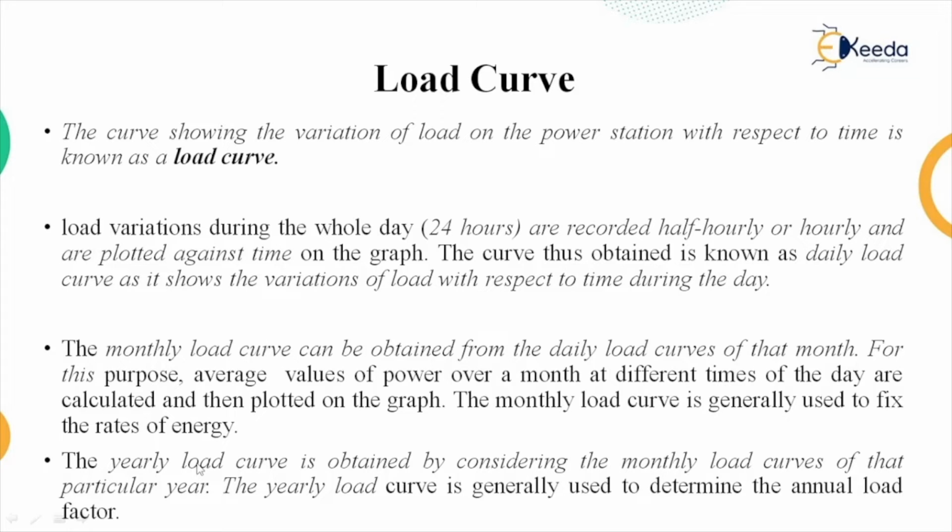Then the yearly load curve is obtained by taking the average of all the months in that year, by considering the monthly load curves of that particular year. The yearly load curve is used to determine the annual load factor. So to calculate the rate of energy we use the monthly load curve. To calculate the annual load factor we use the yearly load curve, and to get the maximum demand of a particular day we draw a daily load curve.